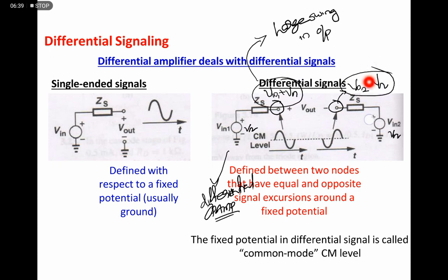That noise is coming from any manner. It is from the thermal noise, or it's from the power supply noise, or it's from the coupling noise. Coupling noise means the coupling between two connecting wires. That will also introduce a parasitic capacitance or coupling effect. That effect also we can reduce using the concept of differential signaling.